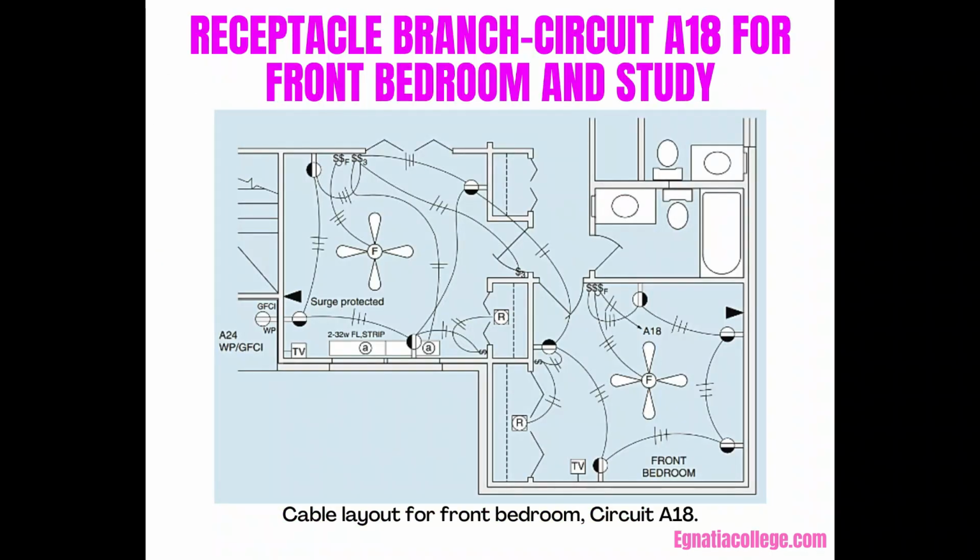Receptacle branch circuit A18 for front bedroom and study. The receptacles in the bedrooms and living room are split-switched receptacles. Half the receptacle, normally the bottom half, is controlled by a wall switch in the room, and the other half is energized continuously.